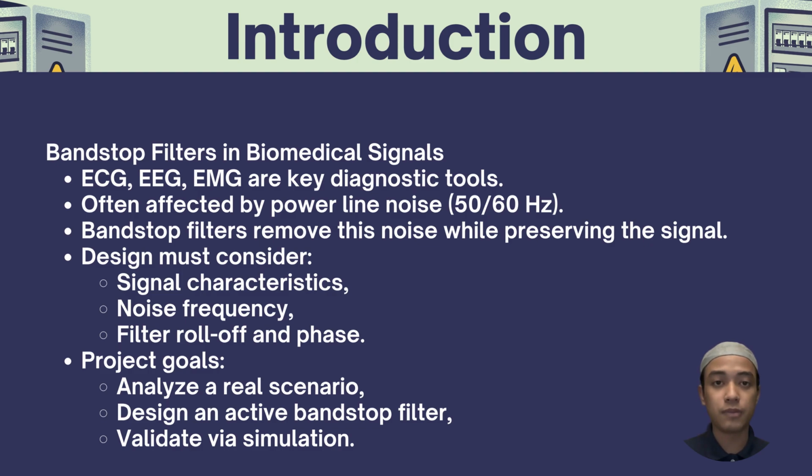For the design, we must consider signal characteristic, noise frequency, filter roll-off and phase. And then our project goal is to analyze a real scenario, design an active benchtop filter and validate it via simulation.